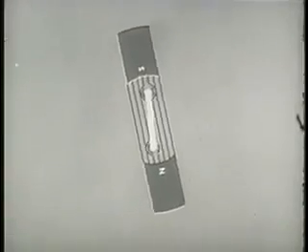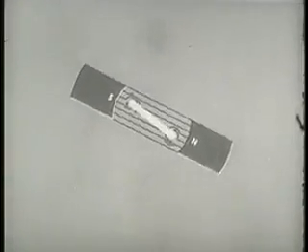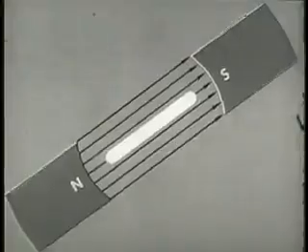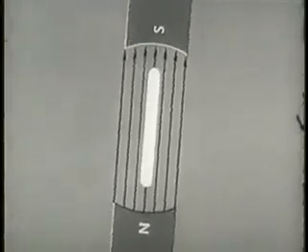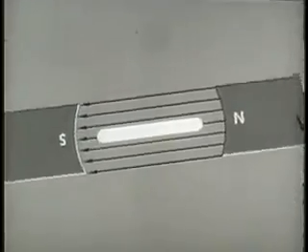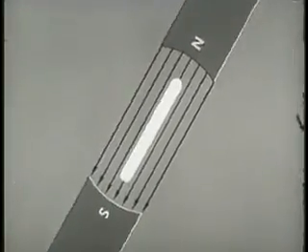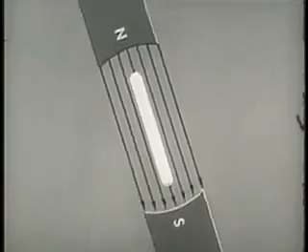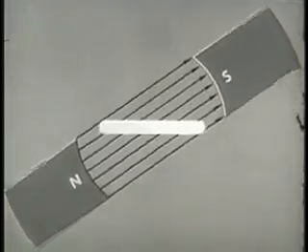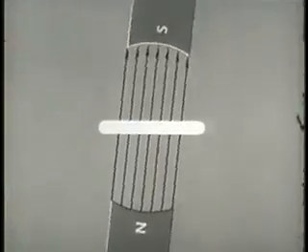The interaction between the conductor fields due to relative motion and the rotating magnetic field causes the rotor to move, but at a slower pace than the rotating field. If the speed of the rotor and the field were the same, there would be no induced EMF. No lines of force would be cut and no field built around the conductor. Obviously, there can be no motor action under those conditions. This, however, is an impossible situation.